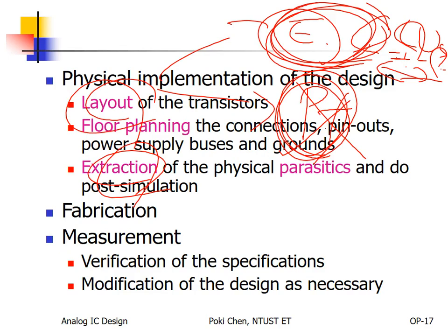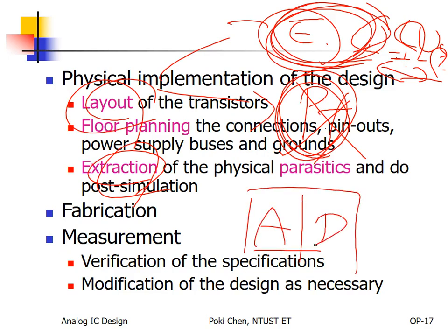But why do I need to mention this? Sometimes such a good understanding can help you speed up the circuit simulation, especially when your circuit has an analog part and a digital part. Usually, the number of devices in the digital part is much, much more than in the analog part. Who controls the accuracy?